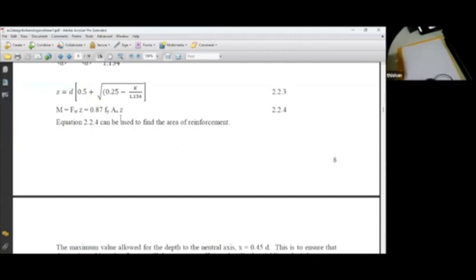And the value engineer will certainly provide all the knowledge needed, but he cannot provide the supervision. Supervision has to come by employing a lot of young engineers who can provide 24-hour surveillance. Even if a concrete pour is done over 24 hours, there will be 3 shifts of engineers who will take over in 8-hour shifts. You can't have one engineer doing, say, 18-hour shifts. You have to have many engineers doing 8-hour shifts, so that the quality controlling and quality assurance part can be properly